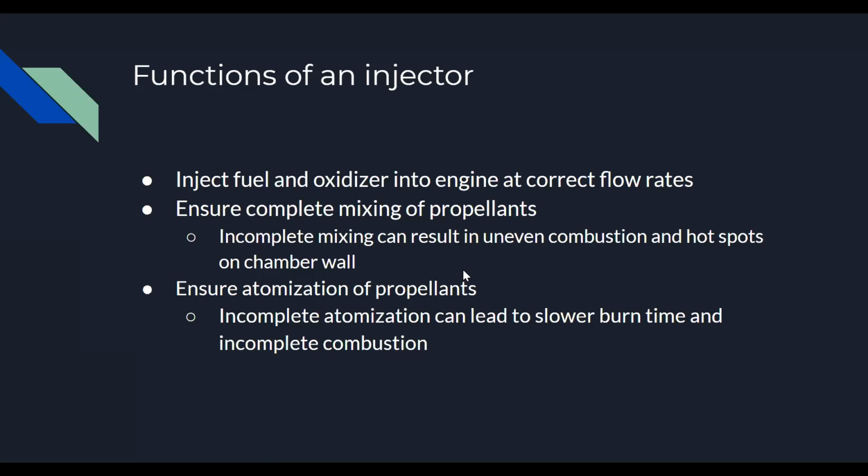And the last thing is it needs to make sure that all of the propellants are atomized adequately, which basically means when the injector injects it into the engine, the propellants are in as small of droplets as possible.